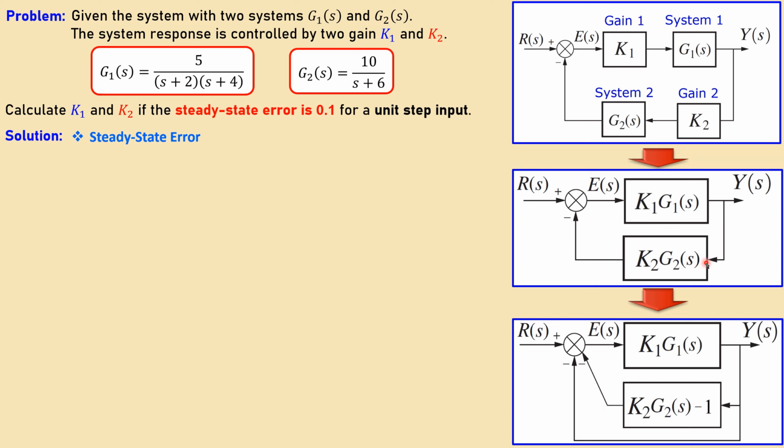You add a minus sign here in the block, and you have a plus here, 1. So you actually have the exact same as before, but this will of course give you now the unity gain feedback. Now what you then do in the next step is, in this box dotted here in green, you call that just an expression for the transfer function. I just call it PS, and that is the transfer function we need to evaluate the steady state error.